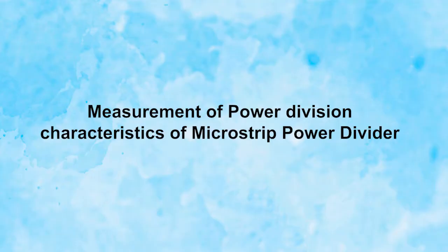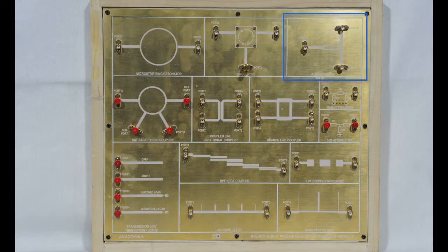Measurement of power division characteristics of microstrip power divider. A 3 dB power divider splits an input signal into two equal output signals. This device has a quarter wave transmission line to effect the split power.